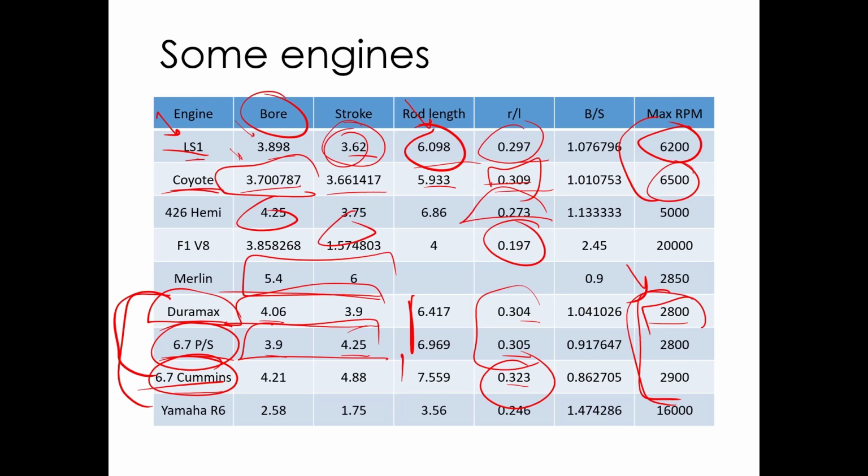So, low RPM, we don't care a lot about the higher order vibrations because there's just not a lot of RPM. There's not a lot of acceleration just because there's not a lot of speed. But what you see is that because there's only 6 cylinders for the same displacement, we've got bigger bores, a longer stroke, and a really long connecting rod, and this gets to be a really tall engine. It's over an inch longer in that direction than the Duramax is. So it starts getting to be a really tall, skinny engine, and it's harder to fit in things than the V8s are.